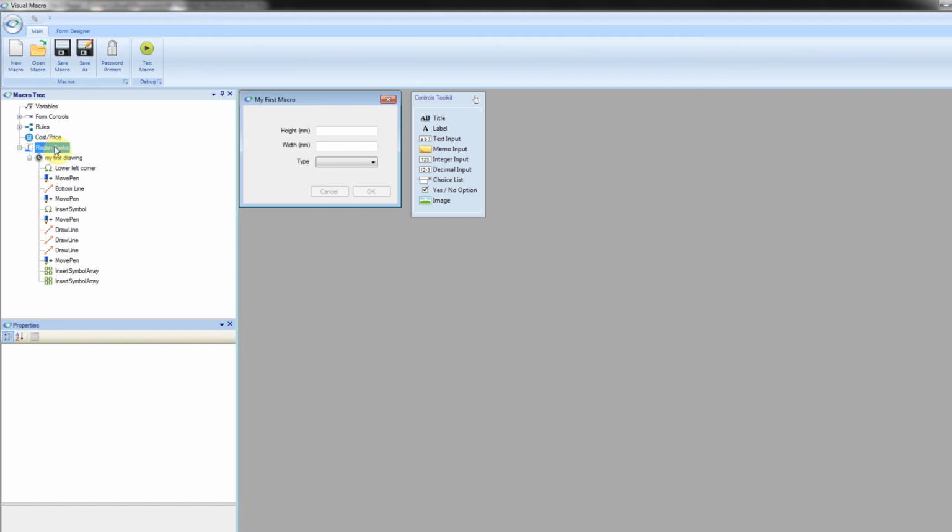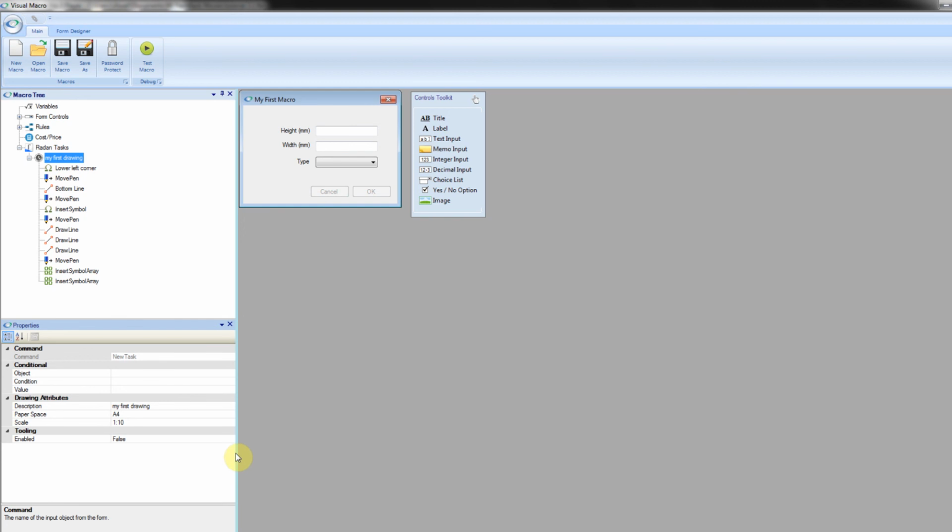OK, now go back to the workbench. You remember that I mentioned the tooling functionality early on in the tutorial. If you enable tooling, then for each drafting command you can specify the tool name and the start and end tags in the command's properties.